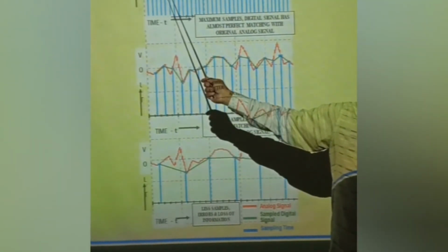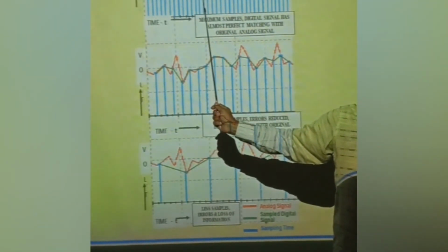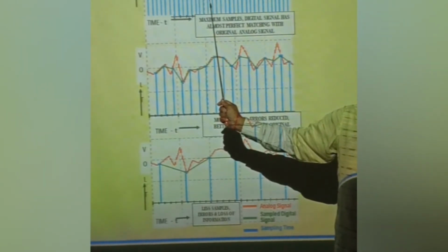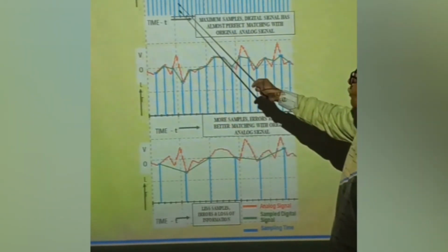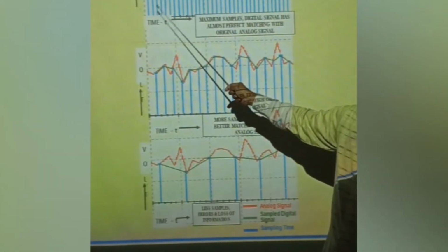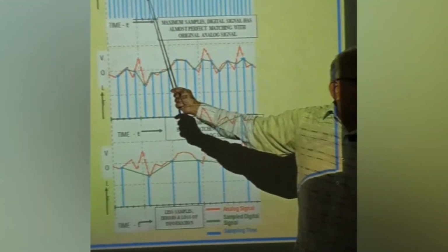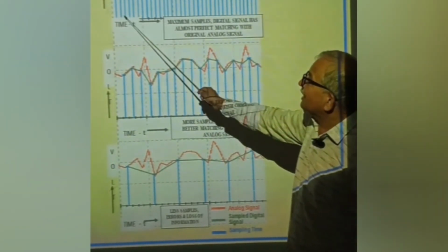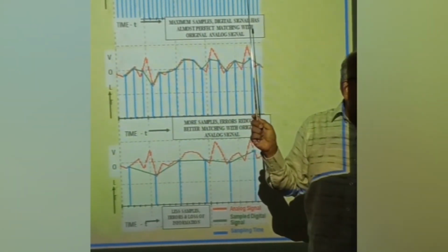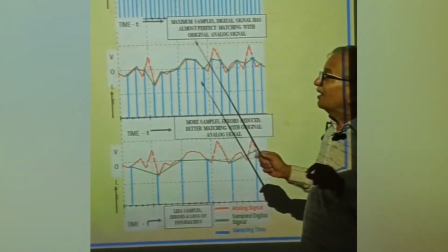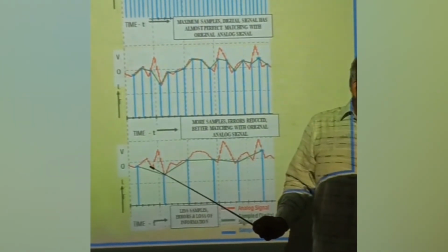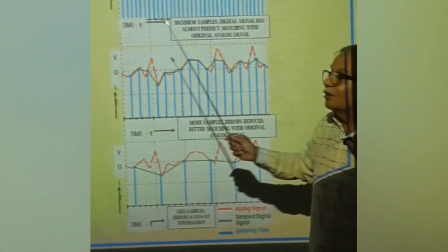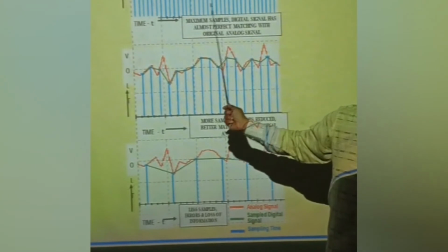A faster and faster sample, if I talk about 8-bit accuracy, one sample requires 8 bits. So 8, if you are working at 1 megahertz, you will require 8 microseconds. Okay, so you cannot take samples earlier. So after 8 microseconds plus gate time and all that, let's assume it is 0, even then 8 microseconds will be the time between 2 samples if you are working at 1 megahertz. Now, if you are working at 1000 megahertz, that is 1 gigahertz, your accuracy will improve. You can take faster and faster samples and make it more and more accurate. So your analog and digital will be better.